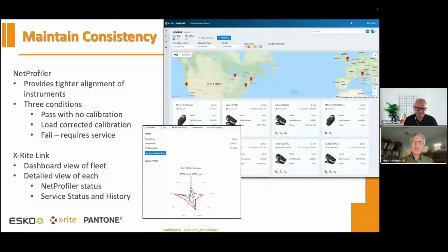Now, if you're measuring materials that have no optical brighteners, the net results can be pretty much the same, M0 and M1. There's no consequence of going one versus the other. They should measure very much the same, because with or without the UV won't impact what the color looks like if there are no optical brighteners in the materials. Okay. If you're working with substrates that have a lot of optical brighteners in the substrates or even in the inks, then you should be using M1 so you can quantify what that looks like. Okay.